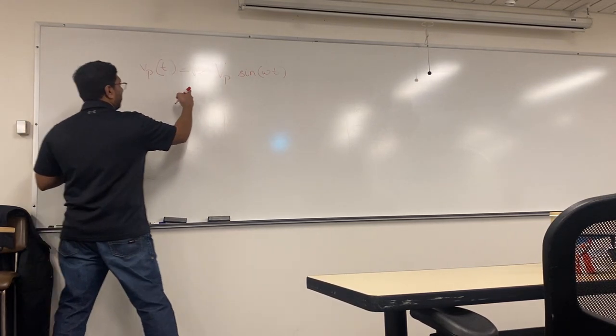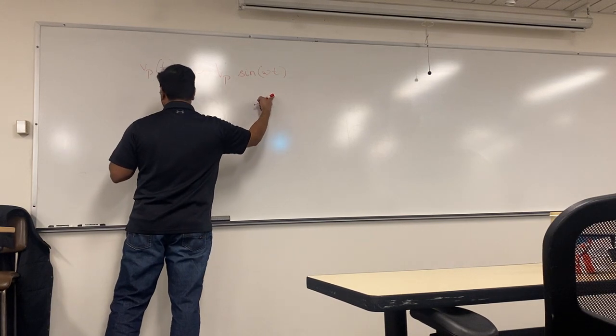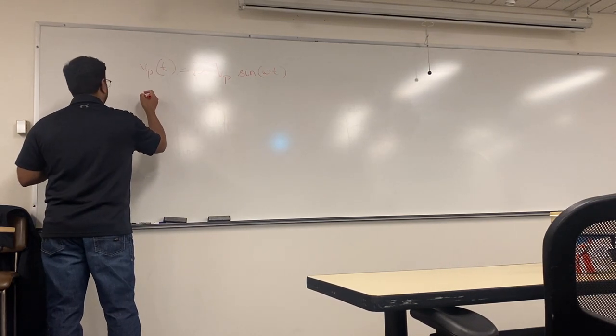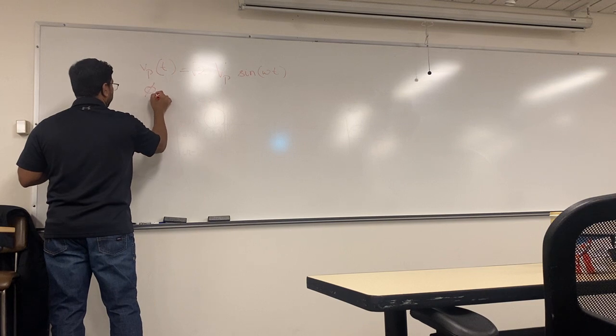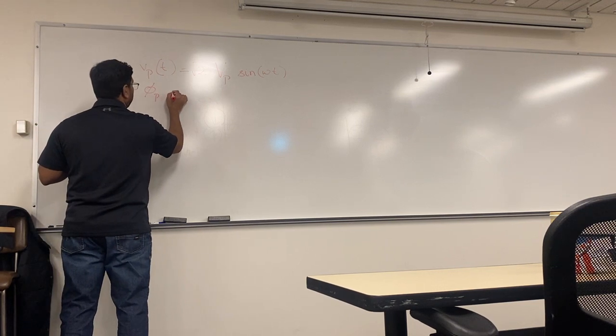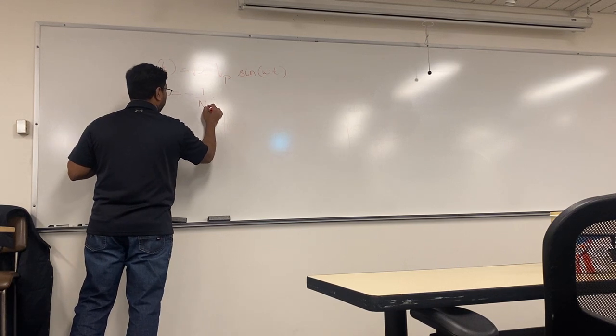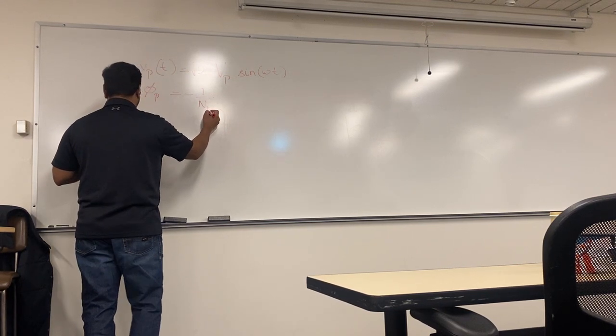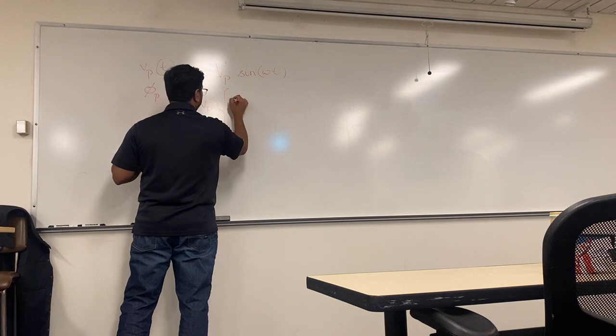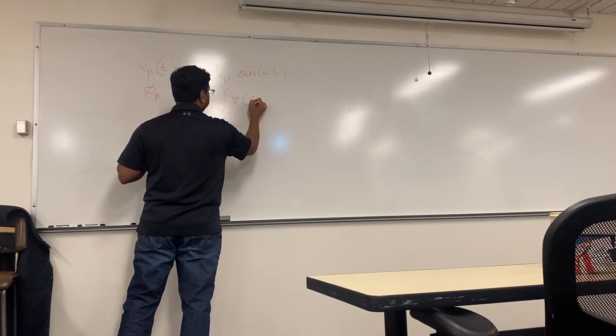So I'm going to apply a sinusoidal voltage on my primary side, and the flux that it's going to generate is going to be negative 1 over NP, that's the number of primary windings I have, times the integral of V of tau.